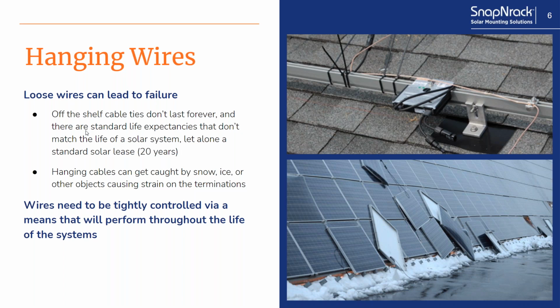Yeah, if you can't see it, it's fine. And to that point, Danny, it's also the materials you're using. You could zip tie anything up, but most people don't know that zip ties have about a shelf life of 7 years, so they're going to deteriorate up there on the roof. So it's important to use materials that are metal, whether it's clips or utilizing rails, to make sure that when you have events, whether it's snow, wind, ice, or critters getting up there underneath, it's not a material that's going to be torn away. I used to always really like those snap and rack clips too, the polycarbonate ones. Those are nice.